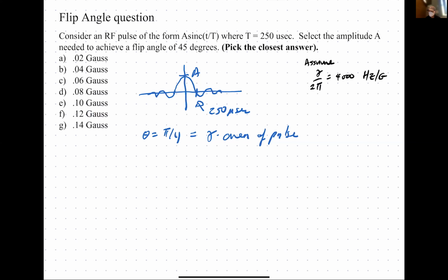Right? So then what we know is we can just say, okay, A sinc(t/T), and I want the Fourier transform of it. I'm going to apply the scaling theorem, so I just get A times T times rect(fT). Okay, so that's applying the scaling theorem. We'll be using the scaling theorem probably the most of any of the theorems in Fourier transform. If you need more information on that, let me know, but there are the supplementary lectures and you can take a look at those.